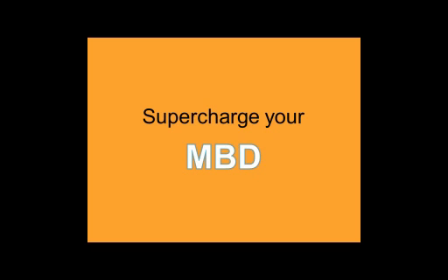Our second takeaway is supercharge your MBD, your model-based definition. This solution works directly from the 3D model. The programming process references the master model in CATIA V5. There's no need to translate or create other 2D drawings to tell your CMM program what to measure and how to measure it. Since I'm working in the 3D environment, I can see all of the model-based definition information that needs to be taken into consideration when generating your CMM program. The CATIA V5 CMM Planner creates a production-ready program that runs natively on virtually any CMM machine.